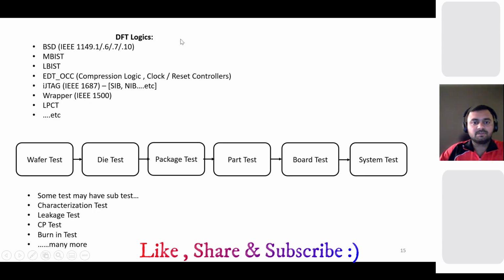So I worked on the DFT side. I'm a DFT engineer, so my discussion will be related to DFT, and I will start in a little bit more depth from here. DFT logic has BST. If you remember the diagram where we have the pad, boundary scan, muxing and all, we will go into detail now. BST is nothing but the IEEE 1149.1 standard.